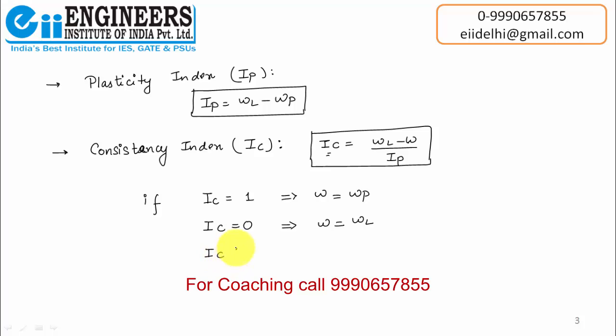If IC is less than 0, then the soil behaves as a liquid, and if IC is greater than 1, then the soil is in solid or semi-solid state.